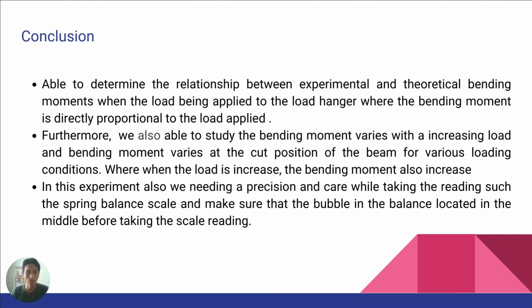The conclusion for this experiment: we are able to determine the relationship between experimental and theoretical bending moment when the load is applied to the load hanger, where the bending moment is directly proportional to the load applied. We can see this based on the graph plotted from the calculation in part 1.